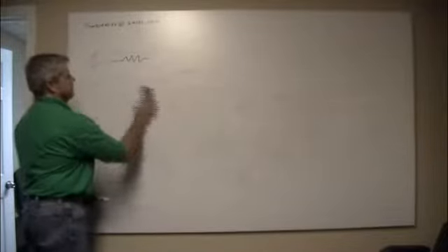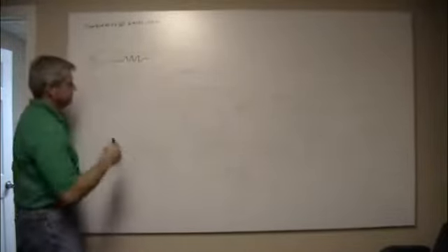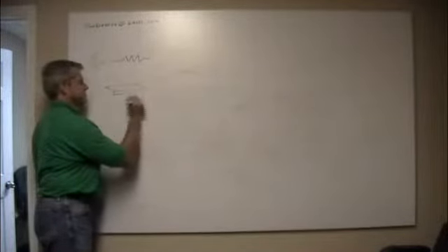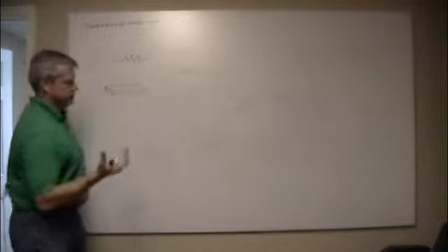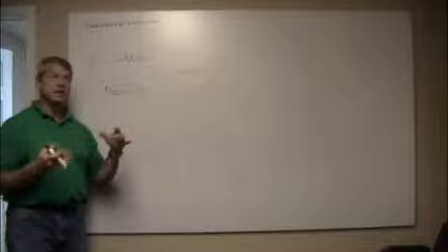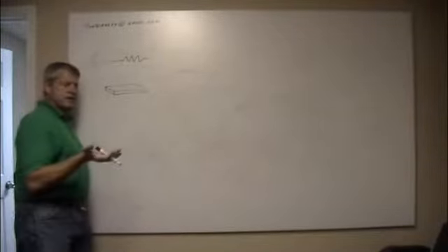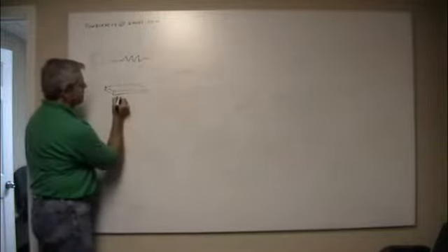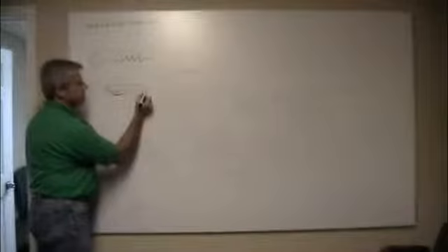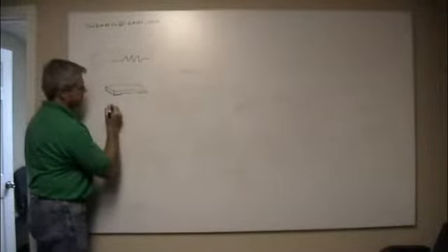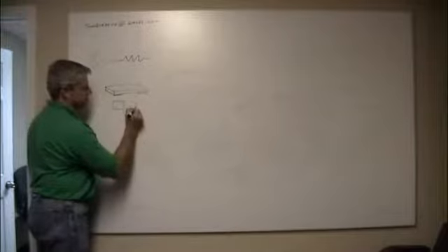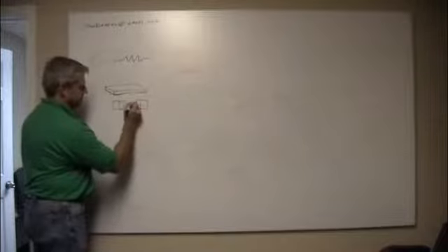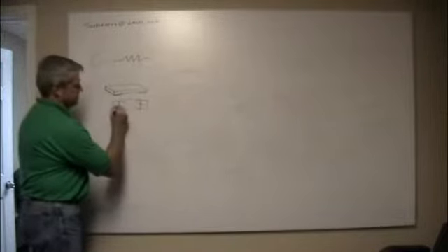Now there's color coding. I'll just talk about this. If you're looking at a surface mount resistor, it just looks like this. And this is true for all of the passive components: there's common footprint numbers. On the underside there's a solder pad that comes around like this on either side, and when you mount it to the circuit board, you've got a spot that looks like this. Your chip will sit right here, and the solder flows underneath it and holds it onto the board.